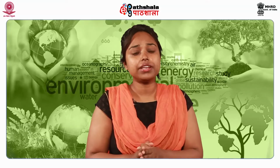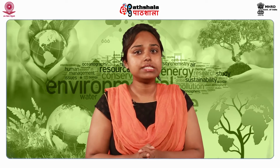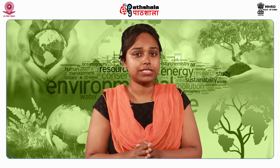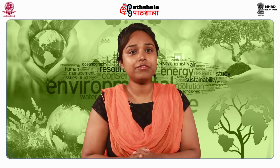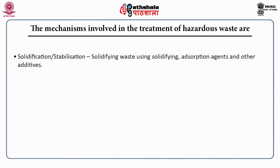The leaching potential can be defined as the natural process by which water soluble substance is washed out from the soil or waste. The process of leaching makes the waste less toxic. Now, let us see the mechanisms involved in the treatment of hazardous waste. First, solidification or stabilization. In this technique, waste is solidified using solidifying or adsorption agents and other additives.